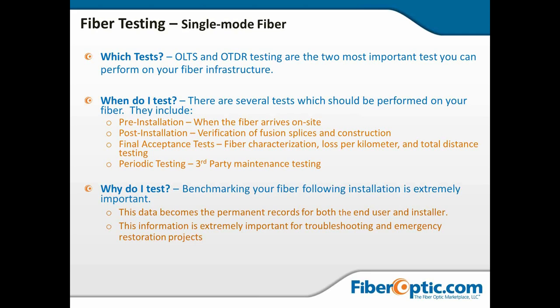specify during the design, and if you're going to be the operator later, you want to look at all of this. And all of these forms, all of these traces, all of this information should become part of the permanent record for whoever the end user is, because this is going to allow us to know what we're supposed to have when we're out testing and troubleshooting. It's the benchmark. It's the best the cable's ever going to look. And that's when we want to save those traces as our benchmark.